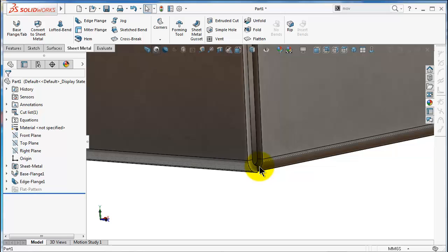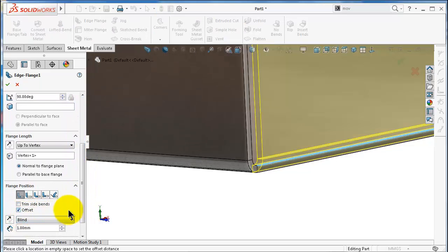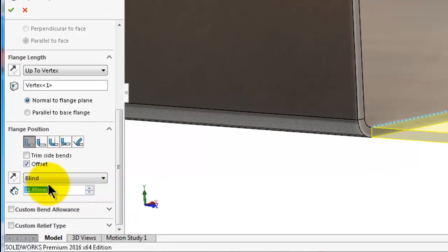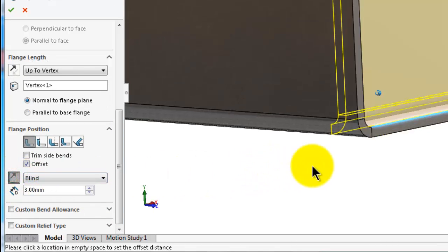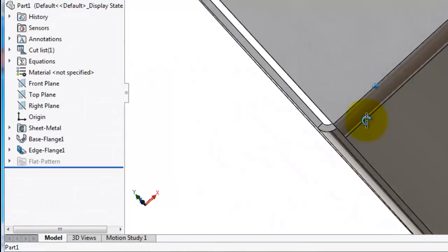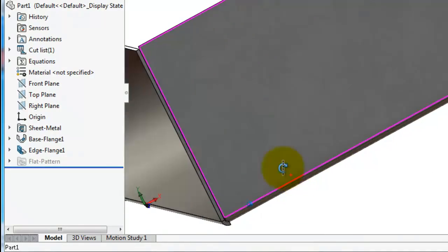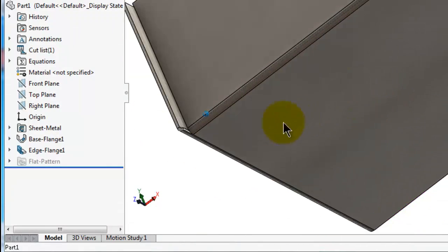So the auto relief is, from its name, to give a relief to the sheet metal while bending and processing. For example, let's decrease the offset of this edge flange, edit feature, and make it with an offset. Make it an offset of 3 mm and reverse it and click OK. So in case of steel, this type of bending might be difficult for such material. So the auto relief purpose is to relieve the corner.